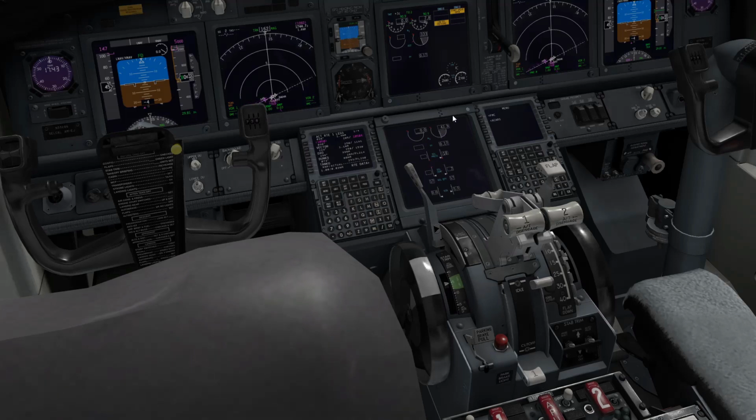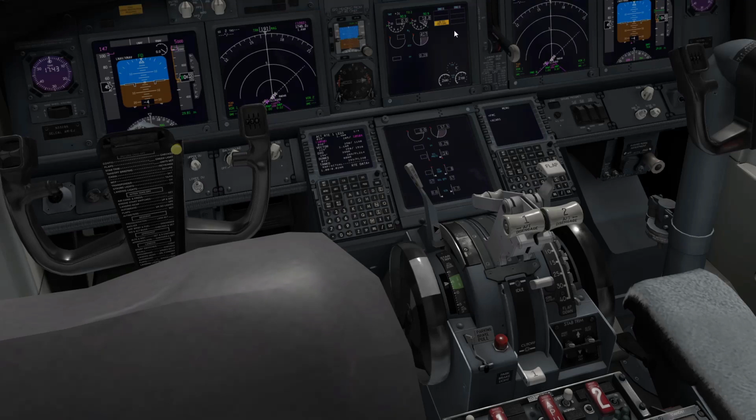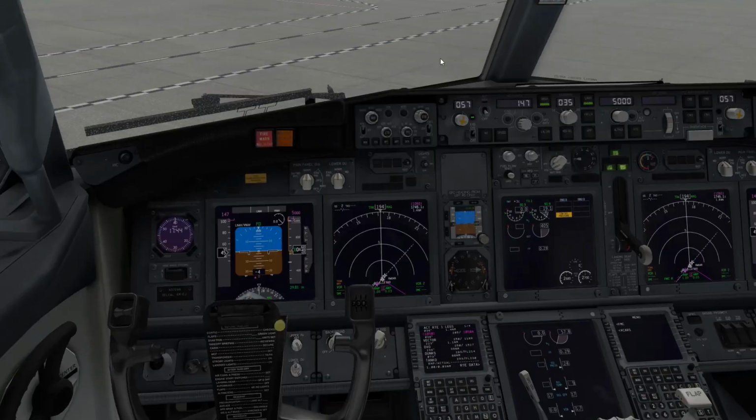Oil pressure's on its way up. And this little tick here, that's the start EGT limit. Once that tick disappears, we know the aircraft has detected a normal start. So the start valve just closed when that light extinguished, and the tick is gone now. So number 2 engine has started.